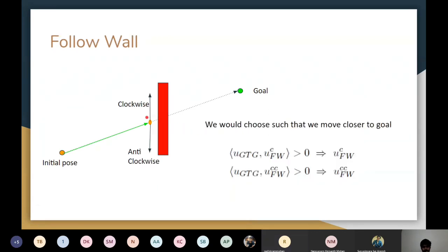Okay. You avoid obstacle. In this case, say the clockwise direction has a direction that is this, and the goal has a direction that is this. Now I'm trying to take a cos of the angle between these two because I need to have conditions in computer language. The condition could be very simple: take the cos between these two, that is the dot product. It's really easy to take.